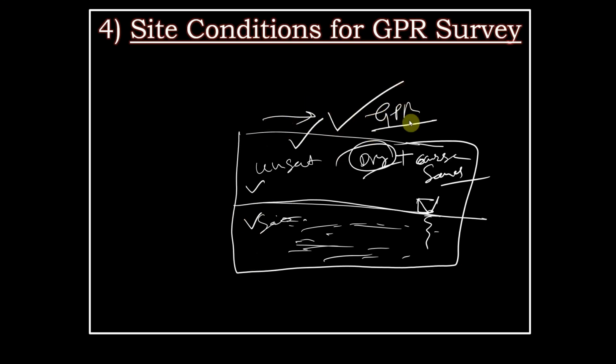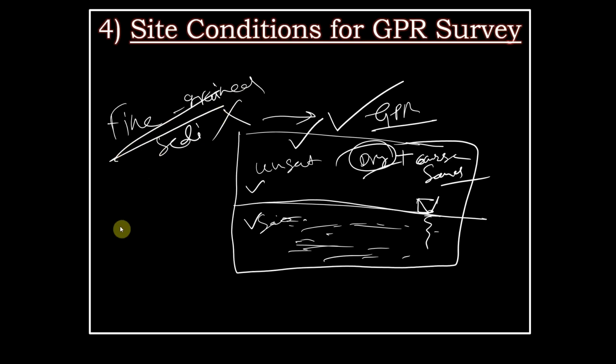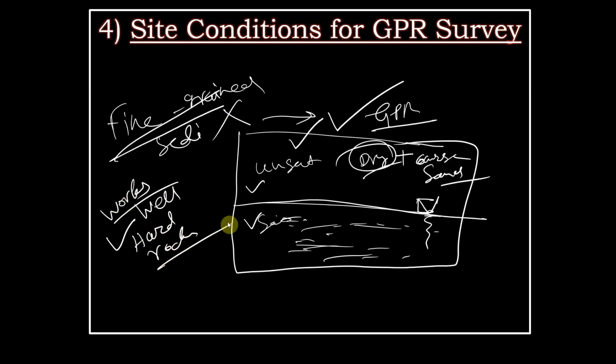So those are the basic site conditions for a GPR survey. You should avoid fine-grained material. Remember one golden rule: fine-grained sediments are not considered. You will not consider a site if the soil cover is fine-grained. GPR works well in hard rock also. The reason will be discussed in another video, so a detailed video regarding this will be coming soon.